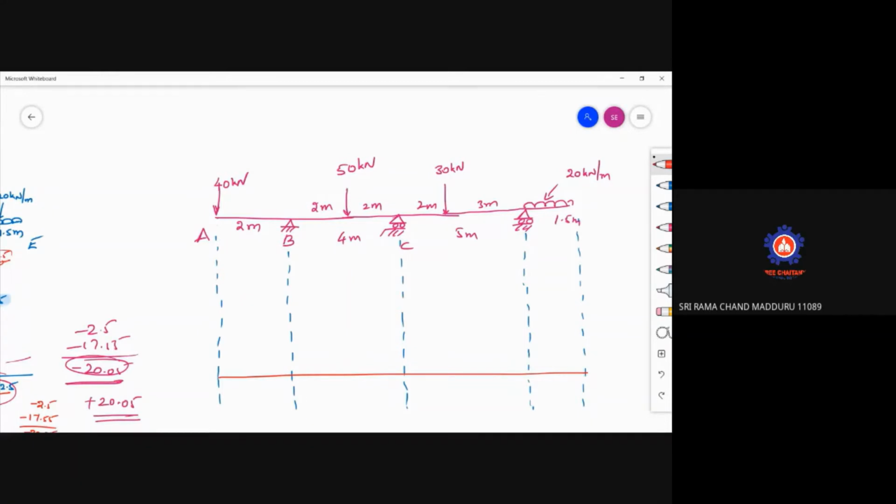First of all, at A, the moment is 0. But as this is creating a cantilever and will bend like this, which is hogging, and hogging is negative, the value is here in the downward direction. So just forget about AB. We'll draw from B to D, then we'll come back once again for DE as well as AB. Let me complete BC first. This is your point load acting at the center, 50 kilonewtons.